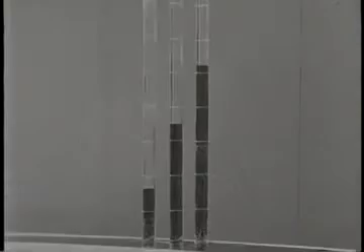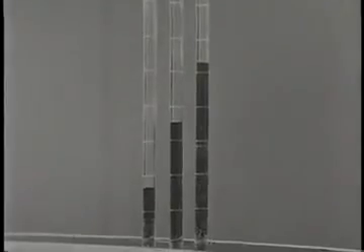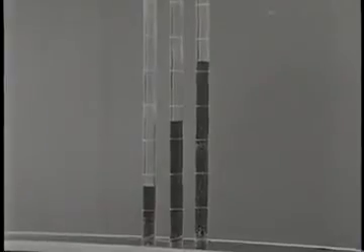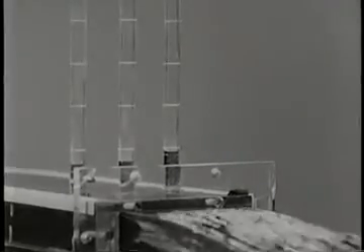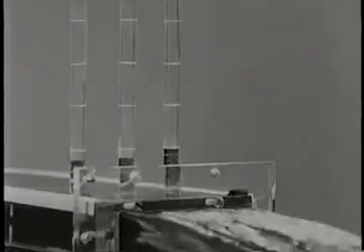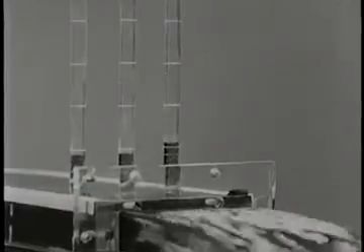At the middle of the bend, there is a pressure difference normal to the streamlines of about 3.5 inches of water. This is close to what we would predict using Euler's equation for the normal pressure gradient. Downstream of the bend, the pressure is almost uniform again. The slight variation there is due to a complicated secondary flow induced by the bend. As we increase the flow, all the pressure differences also increase, according to the square of the velocity. But the pressure difference due to curvature remains a constant fraction of the dynamic pressure.